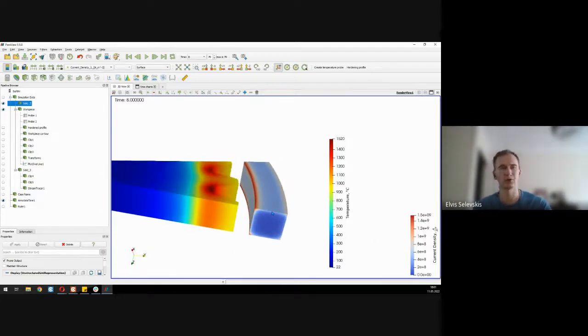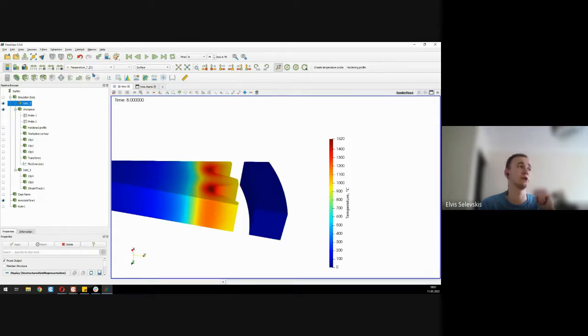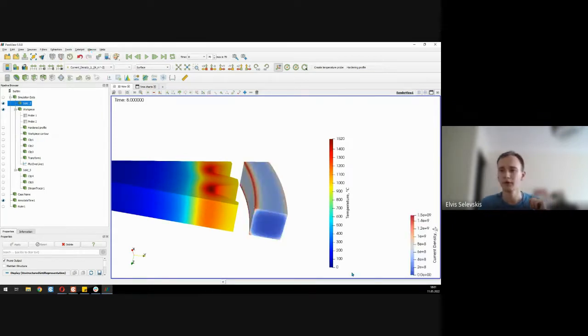That's probably a place where more temperature will also develop, and some kind of problems might occur to the inductor and so on. If you also run a full thermal analysis of the inductor, with cooling on the outside surface and the inside surface, you can probably also check the temperature for the inductor. But about the losses, that's at least the initial things which I would check.